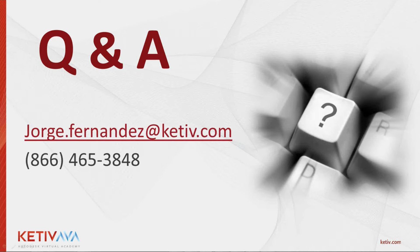We have another question here on weldments. It says, do weld connections have to be established beforehand in the model, or are they established during the connections phase in the FEA? I believe from my experience it's been better to put it into the model. In other words, bring those parts together and simplify it that way, instead of having an actual weld bead on there. I believe that gives you more accurate answers. I don't know, Dave, if you can expand on that a little bit.